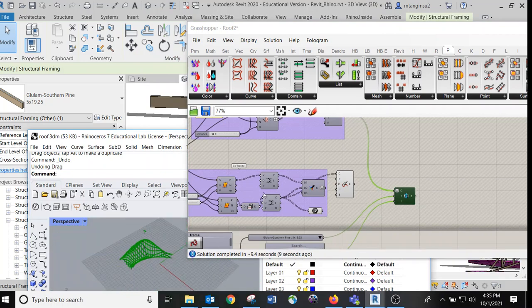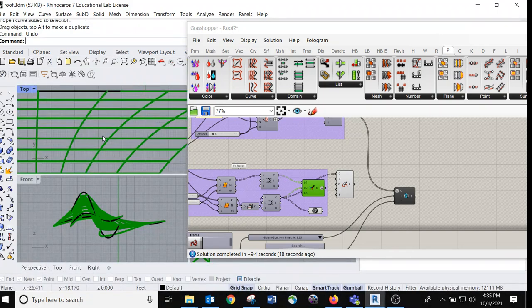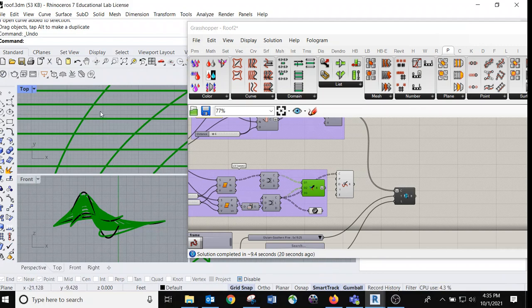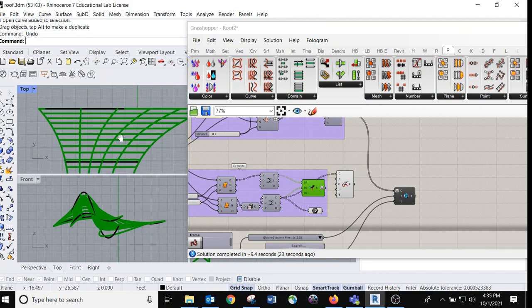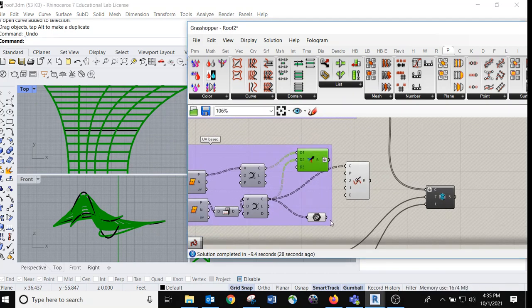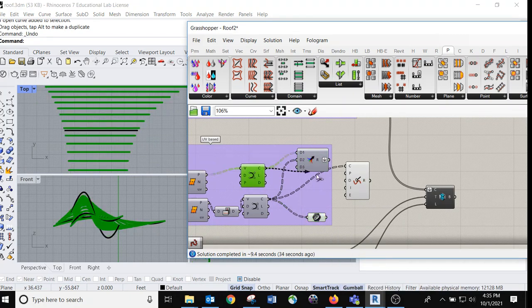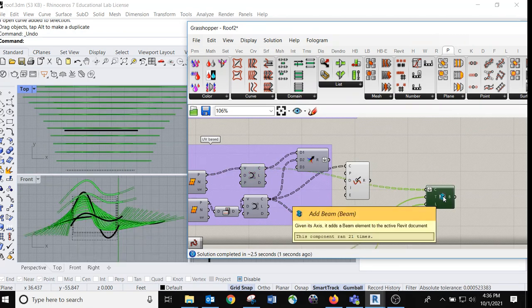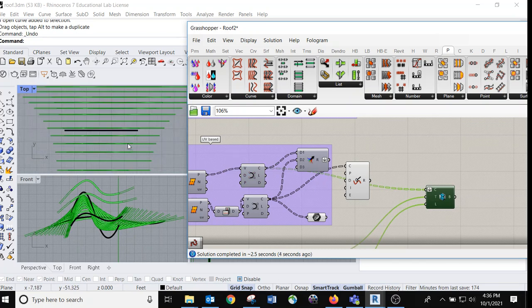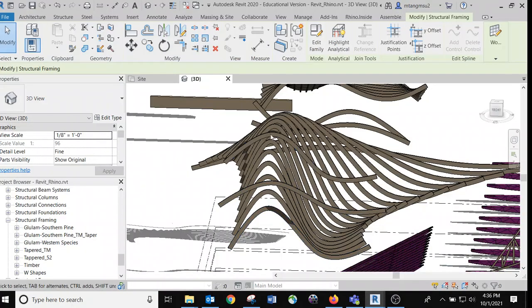See, it's pretty stable. But with UV lines, you can only guarantee, depending on how you constructed the surface. I only see the flat curve along this x-axis, but along the y-axis it is a 3-dimension curve, right? So that's the reason it doesn't work. Okay, so this side doesn't work, but this side should work. Yeah, beautifully. Okay, yeah, see the curve now shows up.